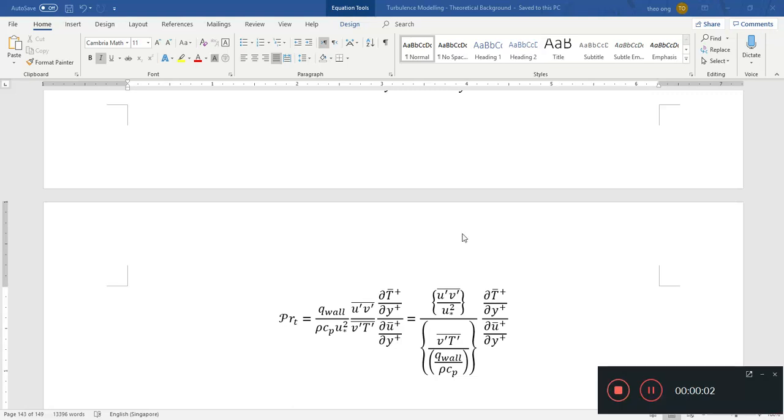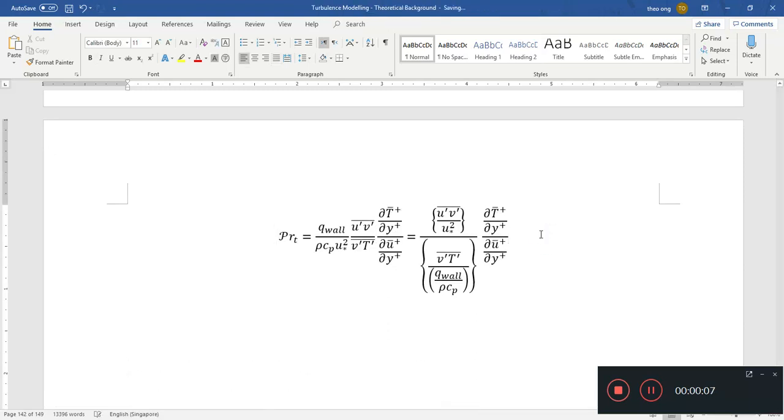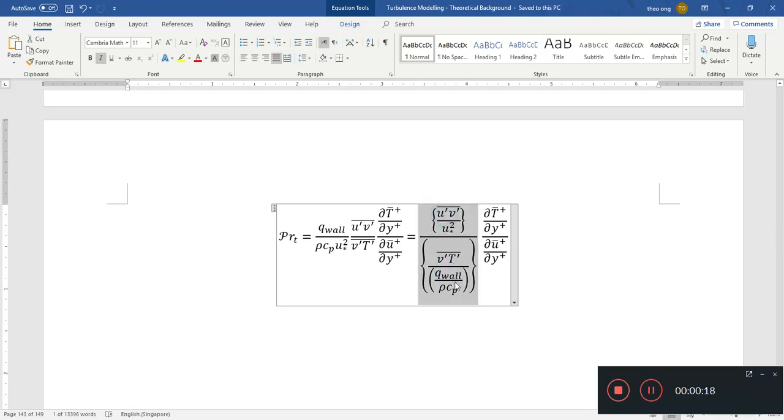Hello, welcome back to this video. We're going to continue talking about heat transfer, turbulent heat transfer. In the last video we talked about the turbulent Prandtl number, and we gave some arguments that by and large this should be equal to about 1 for a Prandtl number of about 1. Because when you non-dimensionalize the disturbances in velocity and temperature, if your Prandtl number is 1, then the mechanism of transport for velocity fluctuations and temperature fluctuations should be about the same.